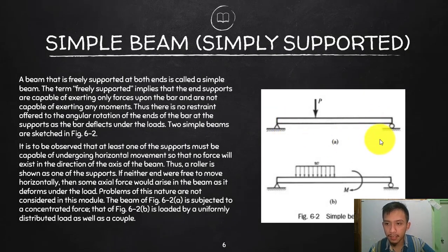In your simple supports, we do not have a moment, of course, since we only have horizontal or vertical reactions. But again, in the summation of horizontal, we will not care about that since there is no horizontal loading. So we will only end up with vertical reactions. That will be included to establish the equations and the diagram. Okay, you can read about that again.